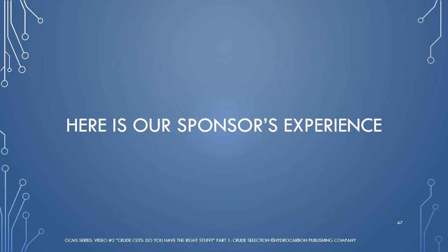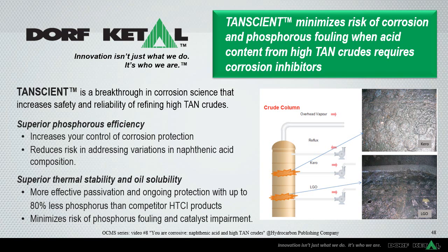Here is our sponsor's experience. OCMS Seminar 1 discussed crude column fouling resulting from addition of thermally unstable phosphate esters used to control corrosion from refining high-TAN crudes. Phosphorus deposits can result from thermal decomposition of the corrosion inhibitor. These decomposition products usually settle out in column trays and can lead to formation of hard deposits that can foul and plug the column.